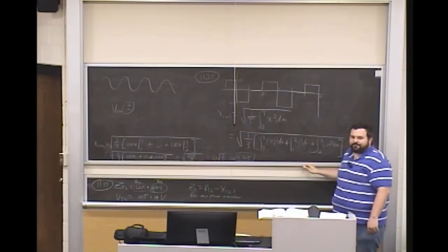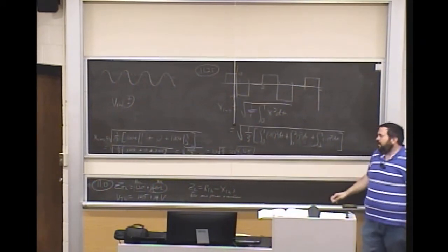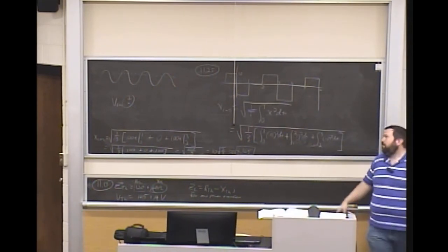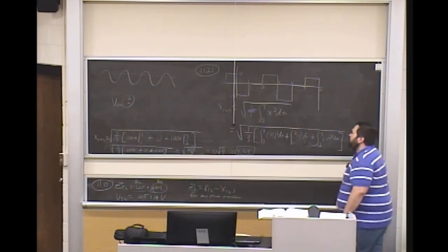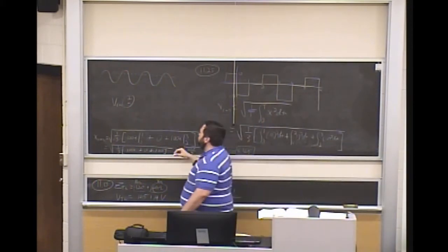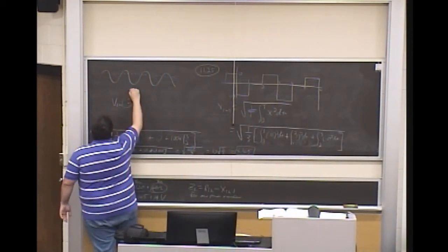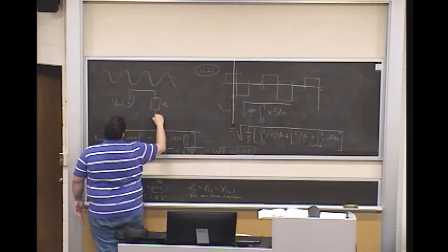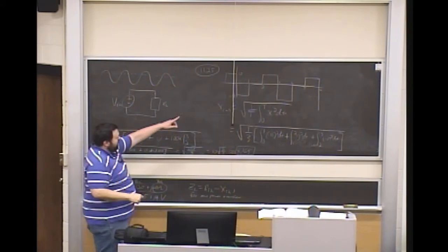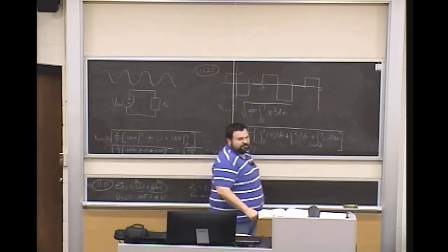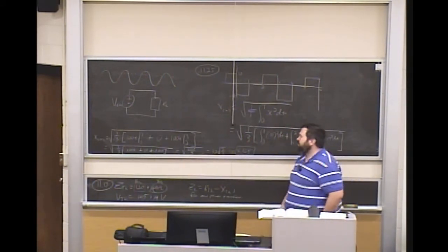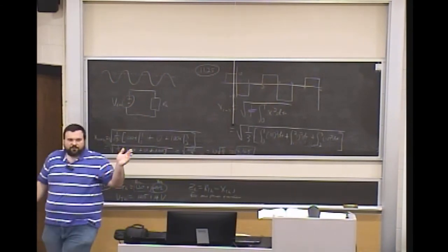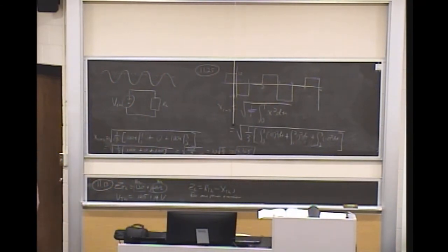Okay. Riley. What's XRMS again? XRMS is the root mean square. So effectively, if this were, let's say, a voltage, and I were to use it to drive some kind of a load over here, I might have a voltage that looks like this. The RMS of that signal is effectively what DC value over time on average would deliver the same power to